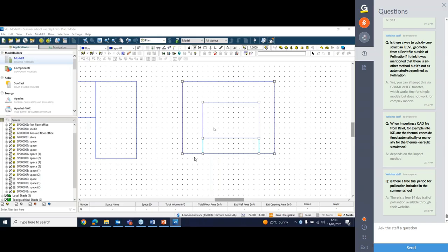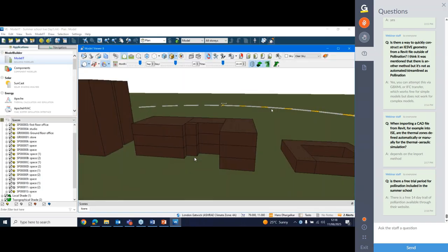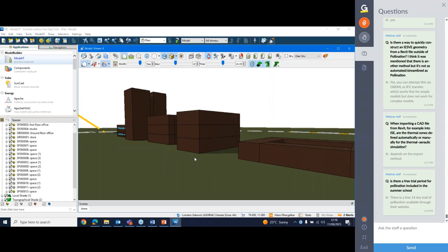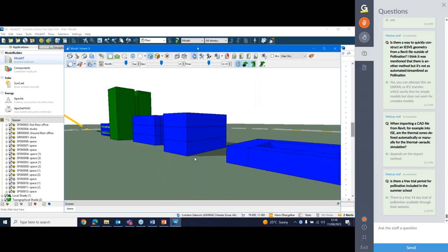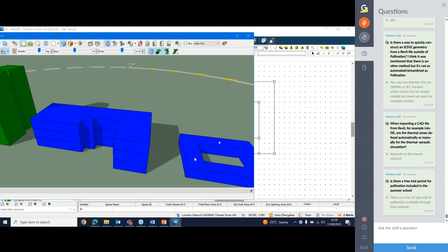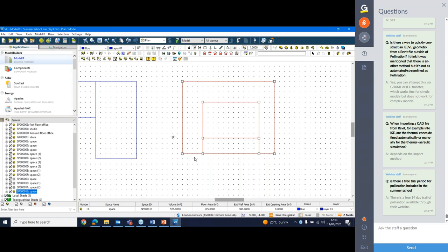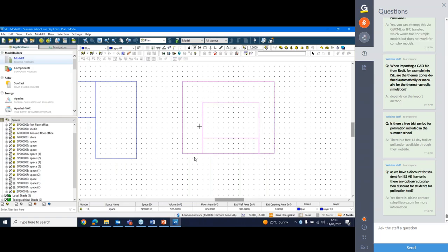But the problem is that if you do a thermal simulation, you will get the average for that square zone. Really, you would split it up into perimeter zones anyway as different rooms with holes between them, because you want to see what goes on the south face and on the north face. So this is not generally a good idea, because you've only got one zone.